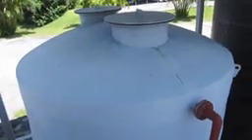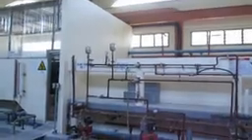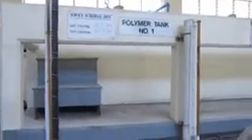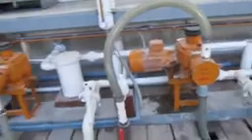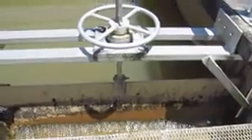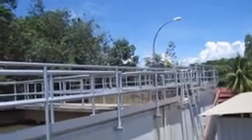Coagulants, usually alum, are added, leading to the formation of microscopic particles in water. This is followed by gentle agitation, causing small particles in the water to collide and combine to become bigger settleable flocs. All polymers used as flocculants in water treatment must be water-soluble. Water solution form. The active polymer in emulsion products is tightly coiled in droplets called micelles. These droplets are polymer emulsified in an oil phase.